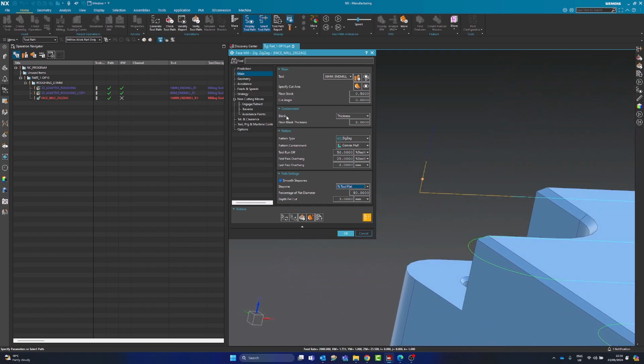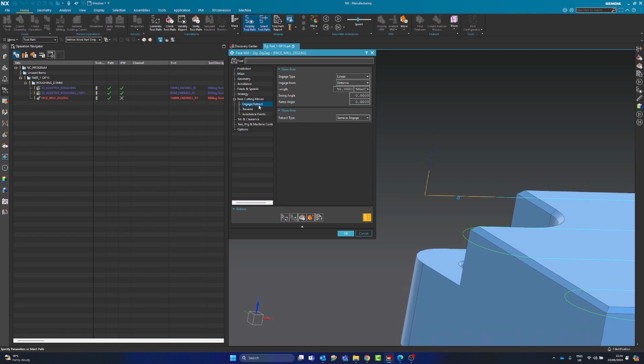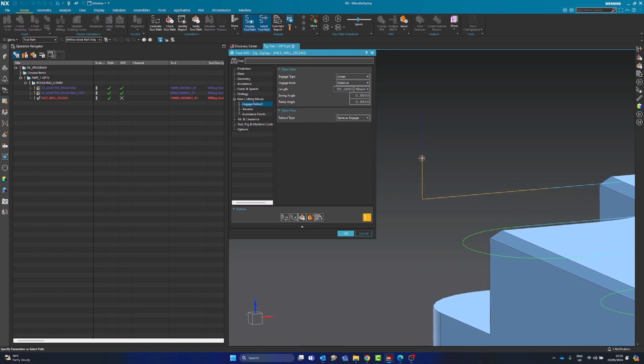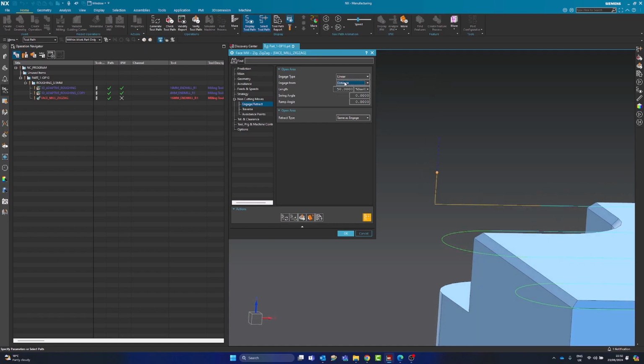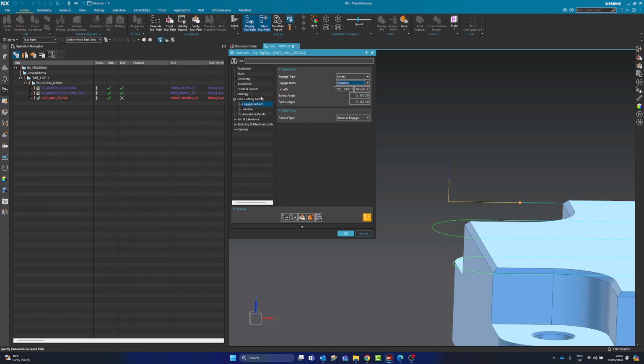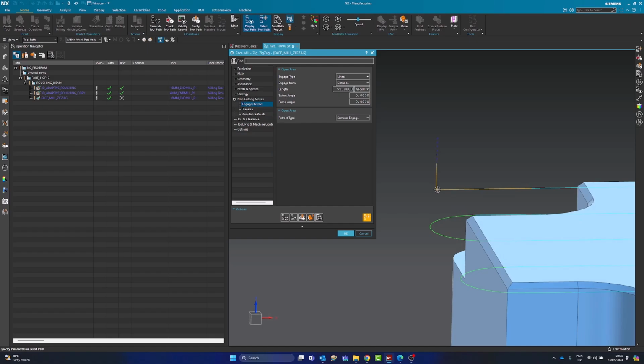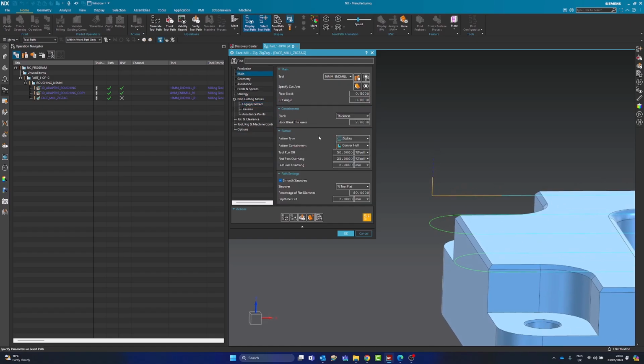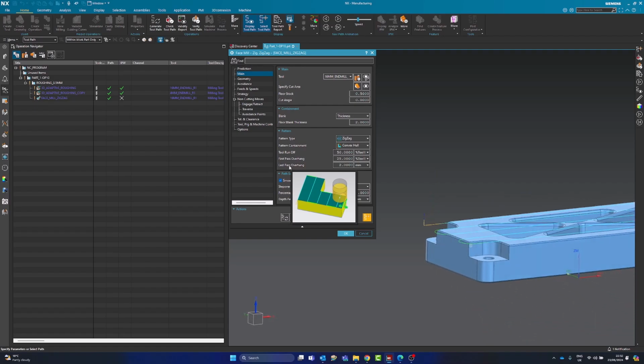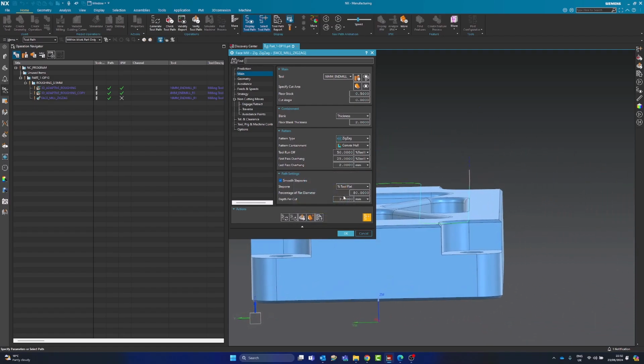I don't like this height, so let's get rid of that. That is going to be in your non-cutting moves, so let's go into the engage. Linear distance, which is this here. Just thinking, I don't see the option for the height here. Is that changeable? Let's have a look through the options. Last pass overhang, that's that 2 mil here. Let's increase that.